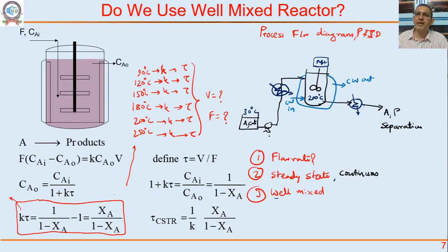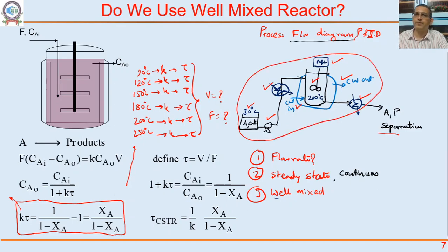This is what I will need to do. Now this is my reactor process flow diagram. So when we say design the reactor, I have to design not just the volume. I have to find the pump, the storage tank, the exchanger. I have to specify the motor, the volume of the reactor, the jacket, how much cooling water is required, how I will cool, and what the separation strategy is. All this is now a part of our reactor design.